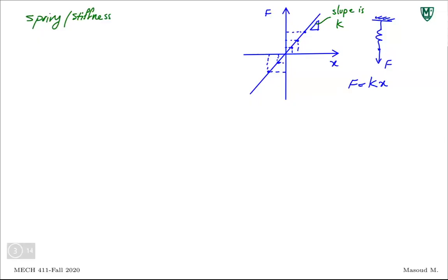The amount of mass attached to the end of the spring is given for every frame. So for each frame, let's say you put your coordinate system using the video tracker to analyze the video. You put it all the way at this end, somewhere here. Let's say you take X in this direction. Then for any given weight, you have the value of weight, which is your force, in this case W, mg, and you measure how much the deformation in the spring is.